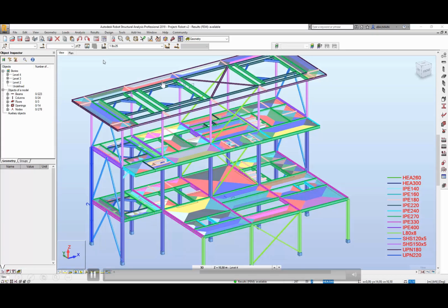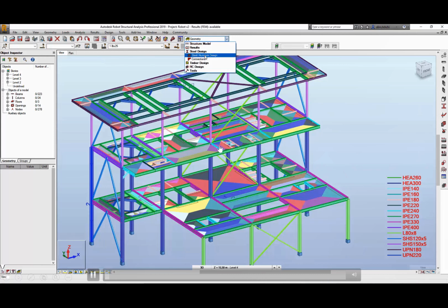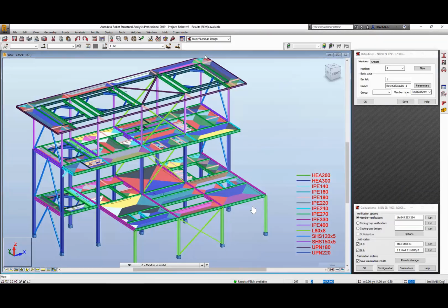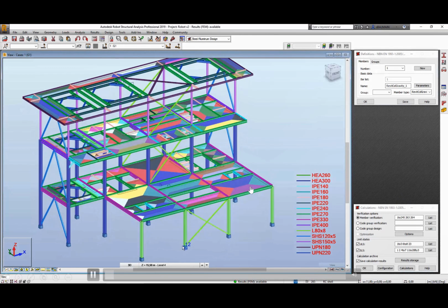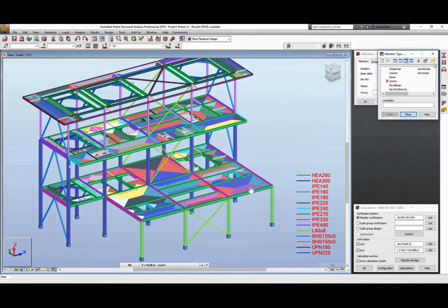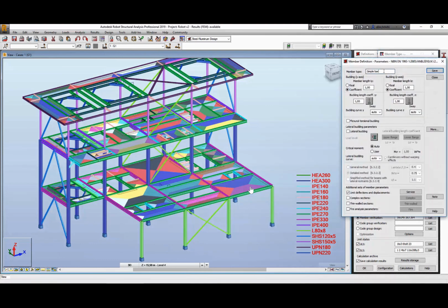When you push that out into Robot, this is what it's going to look like after you're placing those forces on. It's going to show you how those surfaces are warping. It's going to show you if you do have any deflection in your beams or in your concrete. It'll show you exactly where that's happening, okay, so we can make those necessary design changes.